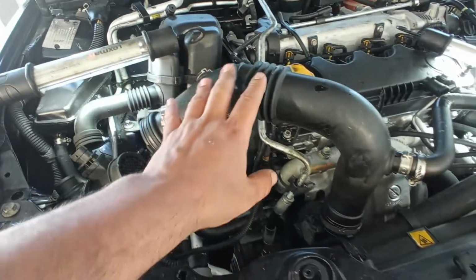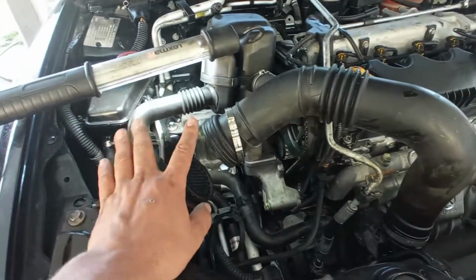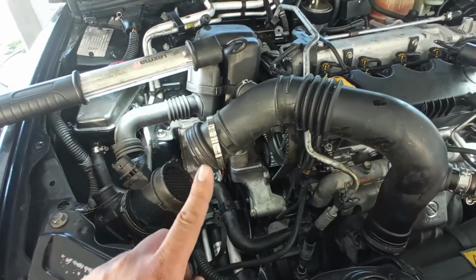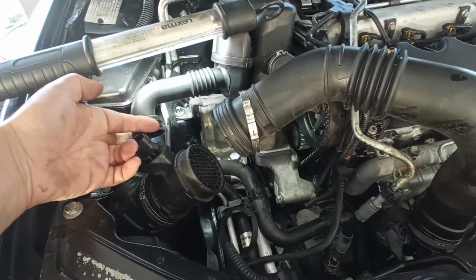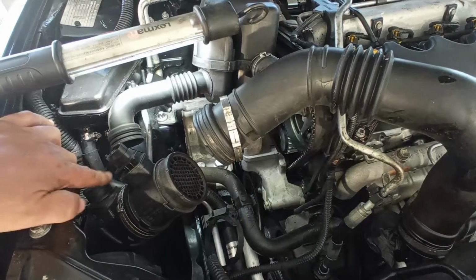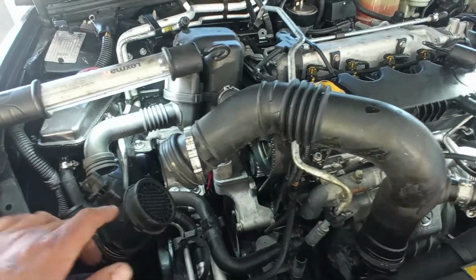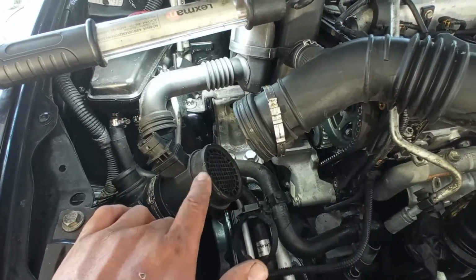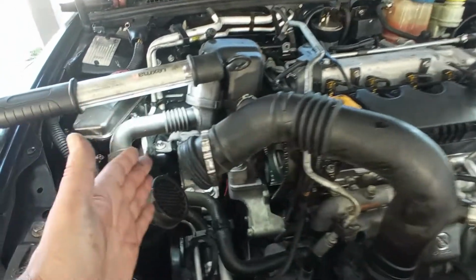And so when removing here this pipe to reach down onto the timing belt, I noticed that this pipe over here had not one, but two false intakes. This clamp over here was not present, which means that air is being sucked through this gap over here, through that resonating box and to the engine, meaning that not all the air is being measured through the mass airflow meter. Okay, so that's number one.